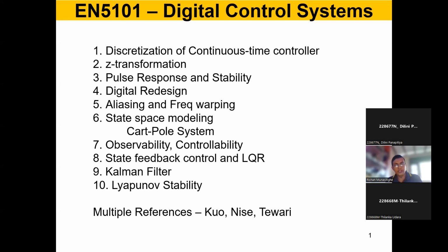And you actually distort the frequency spectrum more than what is naturally happening in any plant, any system, when the frequencies travel from one end to the other. So the moment you bring in the discrete components, the frequency propagation changes further. Therefore, you need to look at what these additional effects are, and control them. So that is number 5, aliasing and frequency warping.